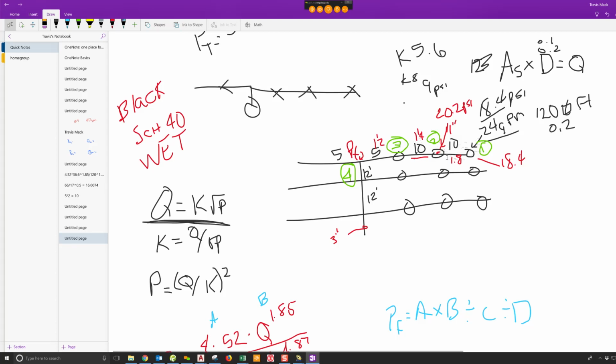Yeah, and what you have to do, and the problems with NICET will all be set up this way, is that you have to verify that you're getting the minimum flows out of each sprinkler. So let's say that this one had a minimum flow of 20 gallons and this one had a minimum flow of 24. Well, we may not have had enough flow coming out of here, and so you have to do some different iterations. That gets more into your level 4 type calcs.